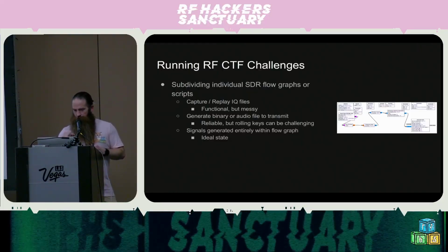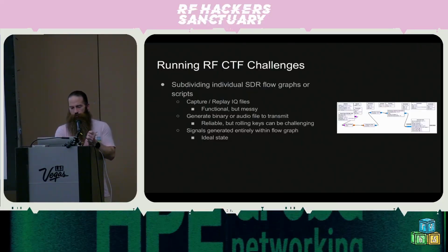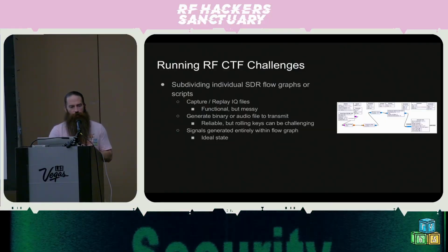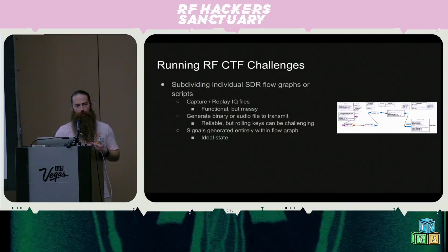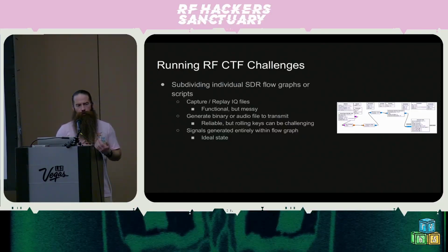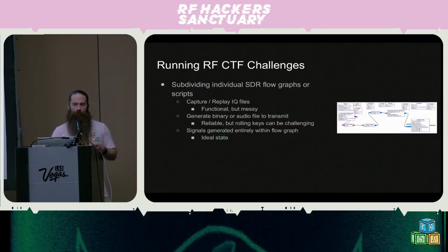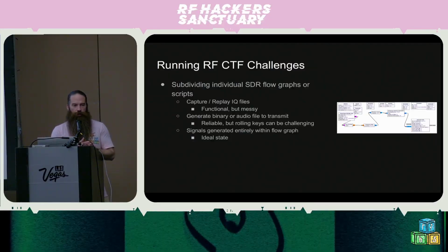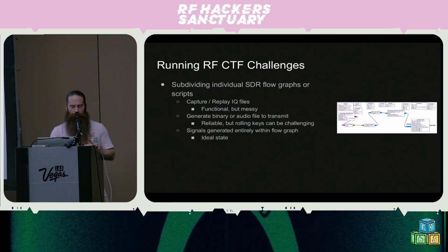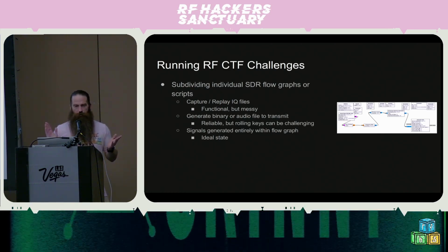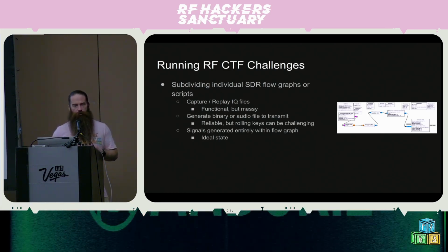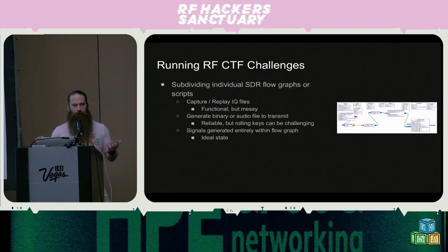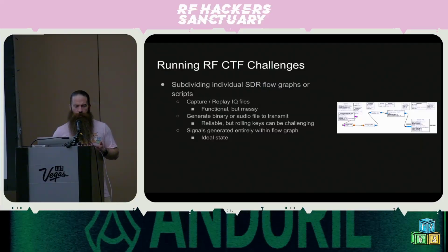Let's see, subdividing individual SDR flow graphs or scripts. When you're creating these individual scripts, there's essentially three different things that you can do with them. You can do a capture and replay. I mentioned the dedicated off-the-shelf hardware. One of the things that we could do with that is capture the raw IQ and just replay that IQ file, just a raw capture, which is fine. That will work. That'll be functional. It's kind of messy, a little bit noisy. If we don't do some additional filtering, then you could be capturing other noise. It's not really the best way of doing things, but it would work.